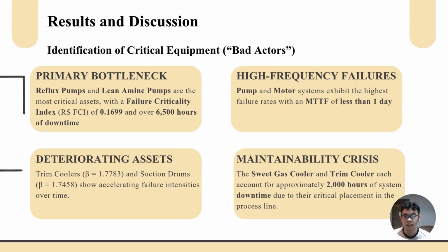Lastly, the sweet gas cooler and the trim cooler each contribute approximately 2,000 hours of downtime because these are static assets sitting directly in the serial process line without bypasses, and their inherent reliability is a major limiting factor for the entire plant.